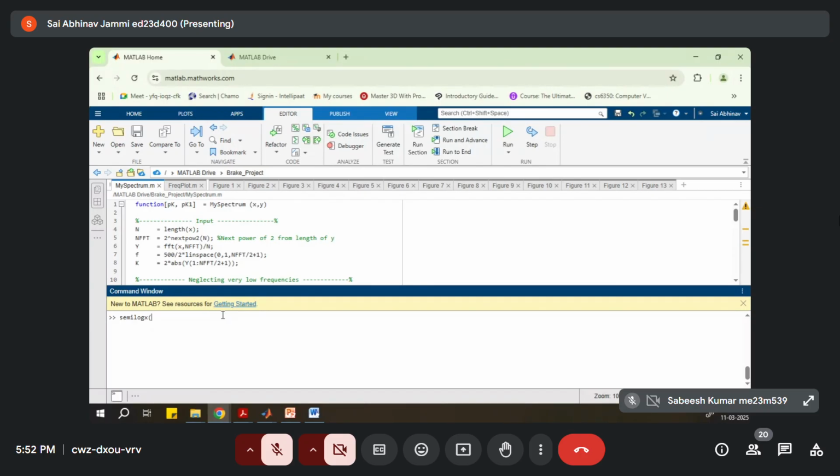So here we have our frequencies ranging from 0.1 to 1.2, right? So that I can give directly as an array, or you can give what is called a linspace. So linspace is short for linear space. Linear space is a function which will generate a vector from a value to a value with these many values. Understood how linspace works?